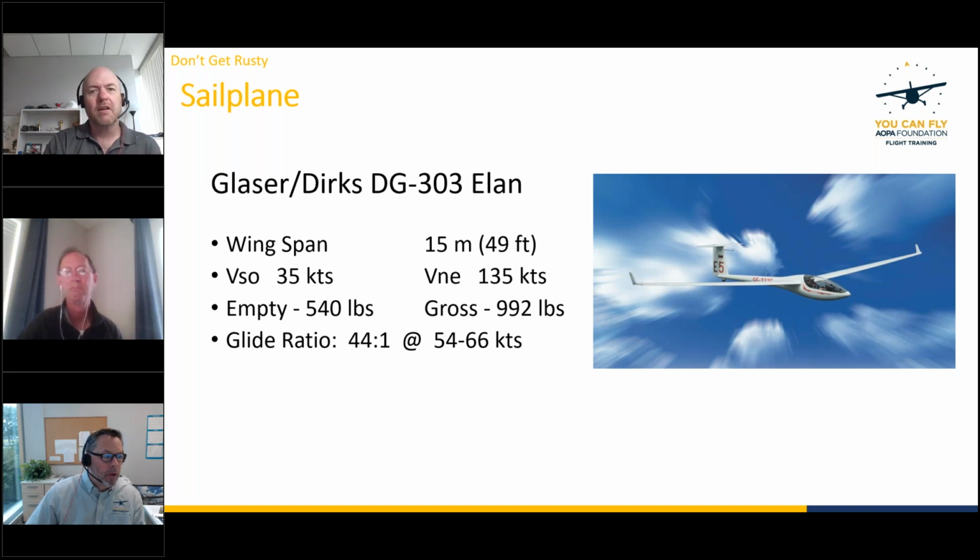Scott had a question come in about weight limit, so I'm glad that you had talked about that. That was an interesting concept, that the glide ratio doesn't change, it's the speed. But someone chimed in and said, I get negative comments about gliding because I'm close to the upper weight limit, about 225 pounds in this situation. Any thoughts as to why that would be? Yeah, it's typically a certification limitation of the aircraft.